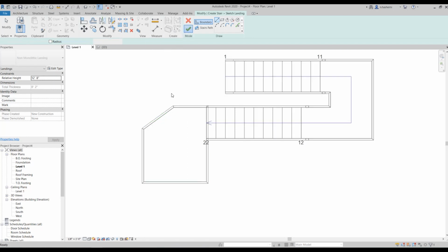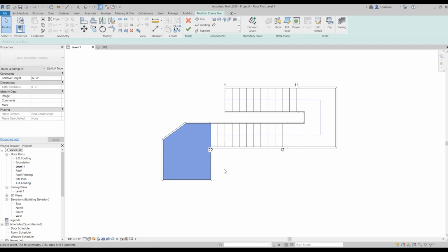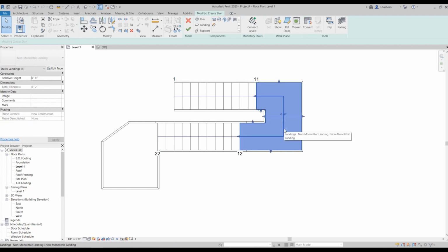And then just hit this green button. Okay. And that was created. Well, actually in Revit, we have other options to edit a stair component like this landing. One way is to convert it to a sketch-based element and then edit the sketch. So we are going to use this convert button over here. Just pay attention that as soon as you click this convert button, it's done, and this process is irreversible.